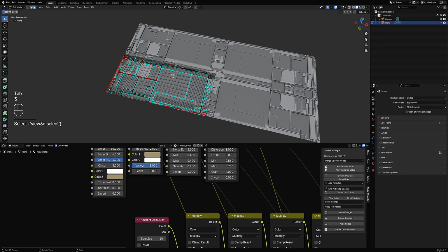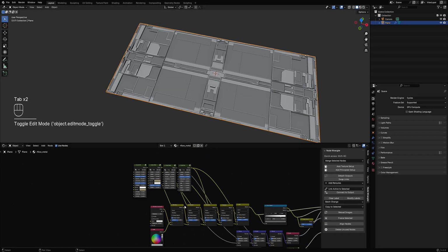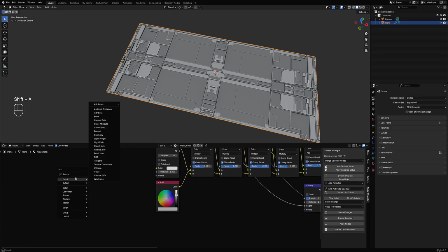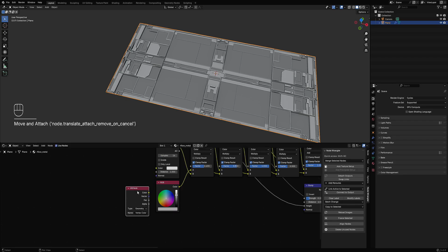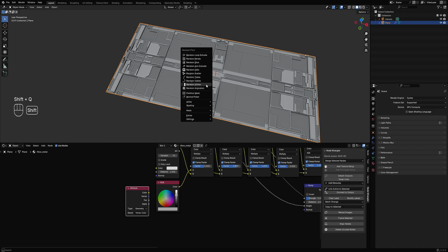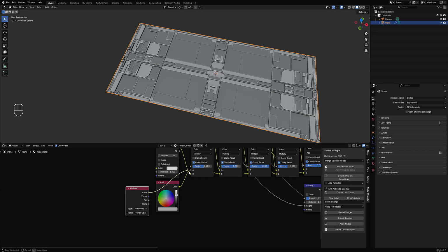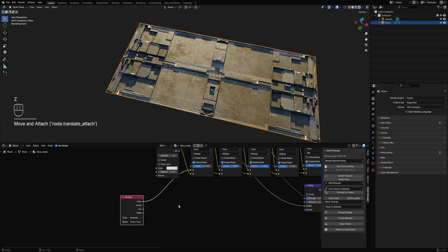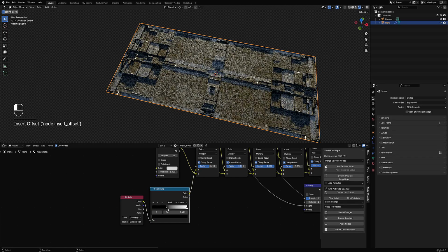Then selecting the face that uses the other material, in this case the airflow material, when using Node Wrangler, we can go to input and this attributes menu will show up and use the vertex color. The vertex color attribute is made using the random vertex color operator. So unplug the color here. You can intensify or change its effect using the color ramp.